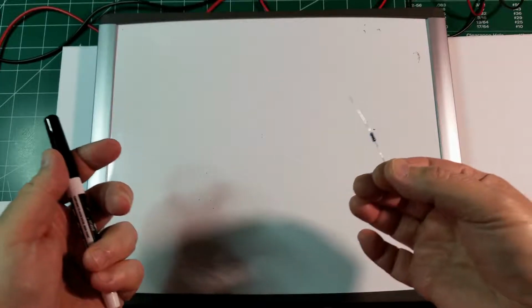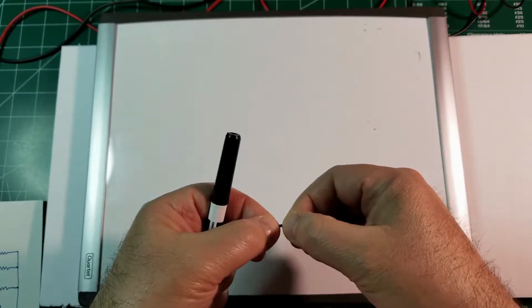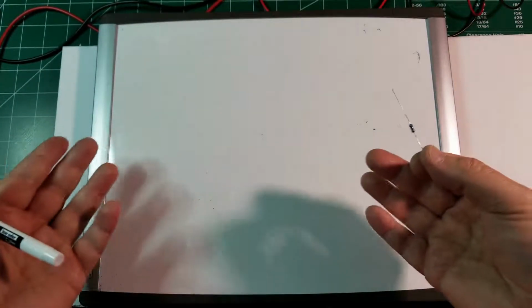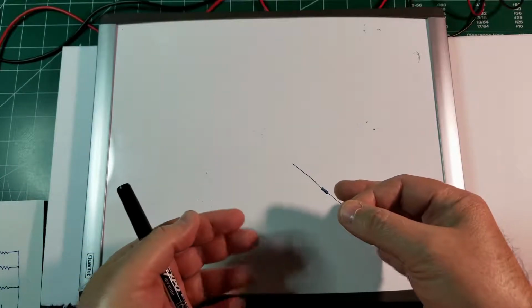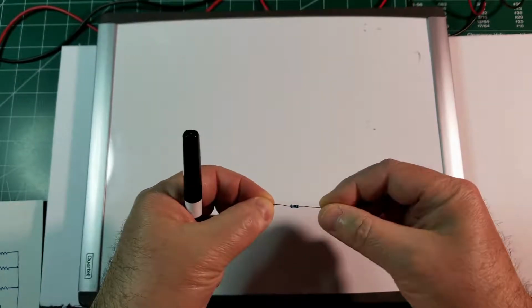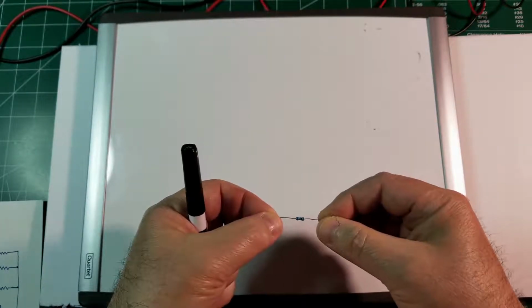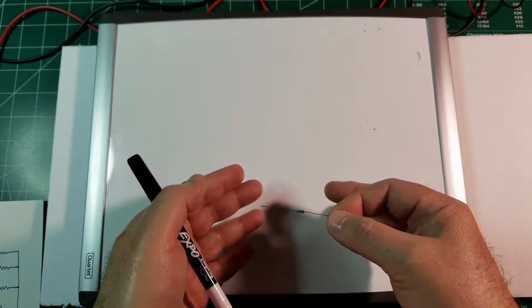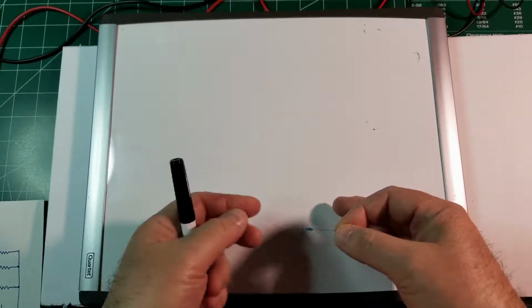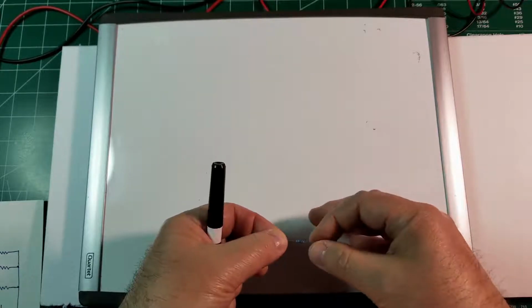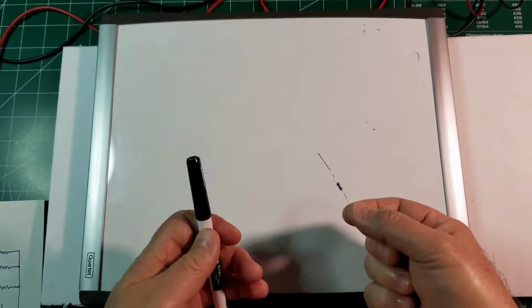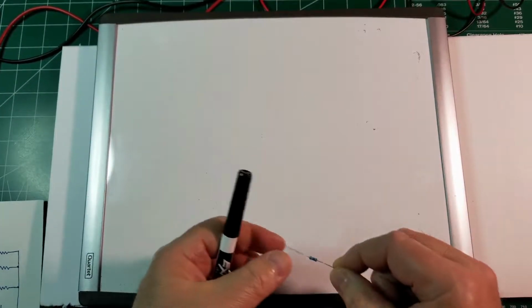In normal electronic circuits, you will never have this kind of voltages. Voltages more likely will go in the term of 1 volt or even less on a single resistor. So basically, you never hear in general about voltage ratings for resistors, because for normal applications there is no need to. However, know that there are this kind of limitations. So if one day you are going to work with high voltages, let's say above 200 volts, know that you have to use the right resistors, otherwise they will break, they won't work anymore.